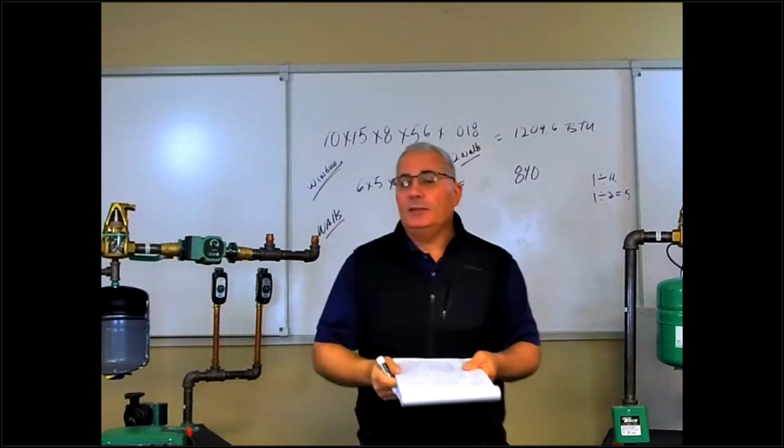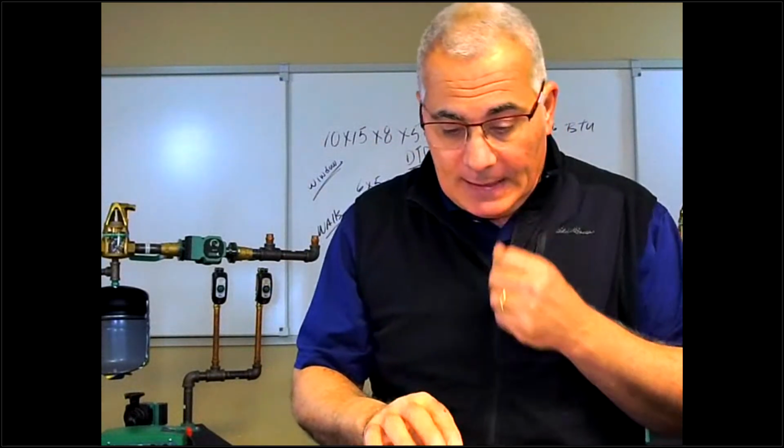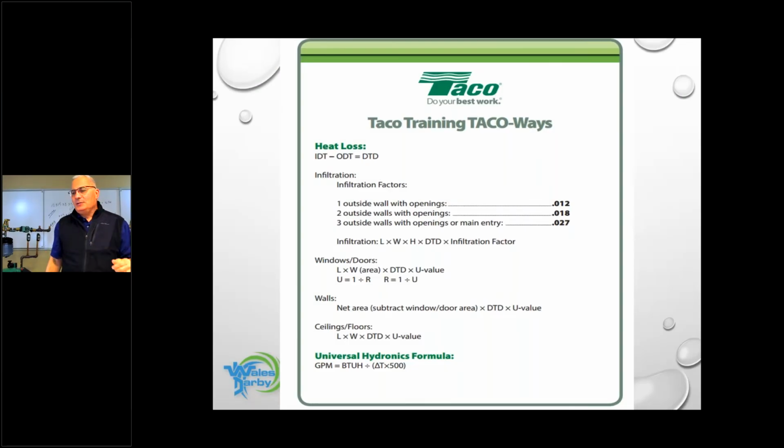Now, again, we have to find out what the U value is for the walls. So let's talk about wall construction. If this was new construction, standard construction methods now is a 2 by 6 wall. 2 by 6, our R value is generally 19. If they tell you they're going to spray foam, maybe 1 inch, and add some insulation on top of that, we can get up to an R25 or higher wall. If you're not 100% sure what the R values are, because new plans that we get don't normally tell us, look at the framing. If you see 2 by 6, minimum should be R19. If you're doing renovation work and you're seeing 2 by 4 construction, well, you're starting off at either R11, maybe a 15. But if you're not sure, you got to poke around. You got to go look. You got to ask.